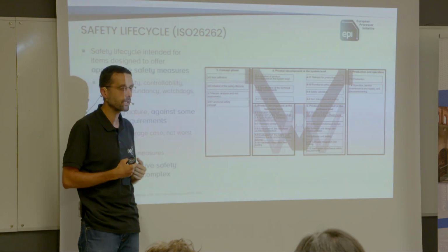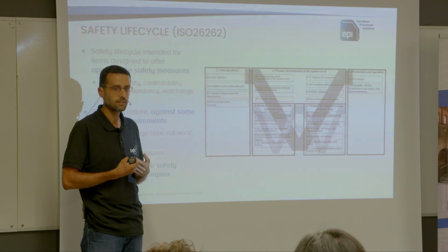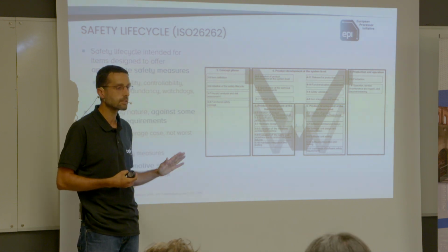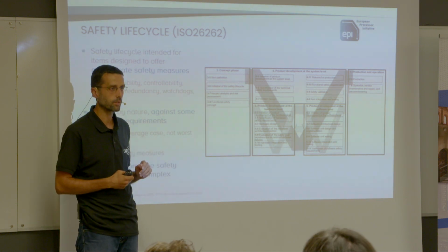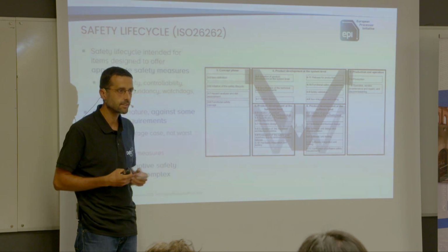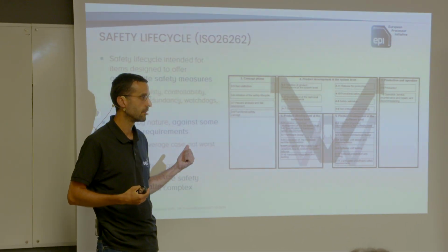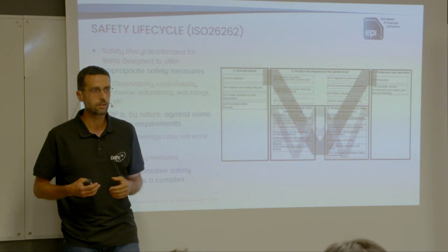You define just these items. And then you start performing what they call a risk and hazard analysis, just to see what kind of things can go wrong. For instance, I press the pedal, and no signal arrives to my computer. Okay? Just these kind of silly and basic things are the starting point. And from there, they start deriving what they call the functional safety concept.